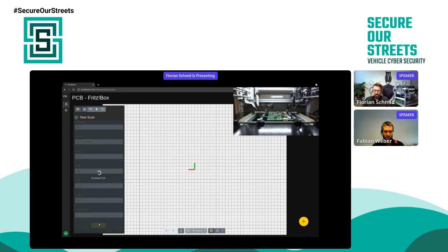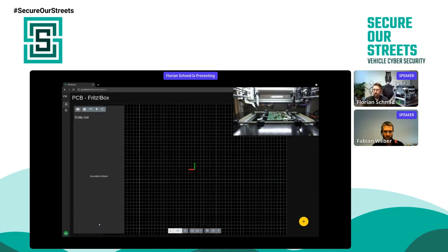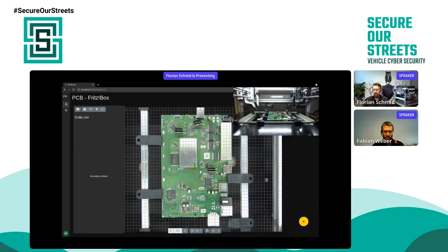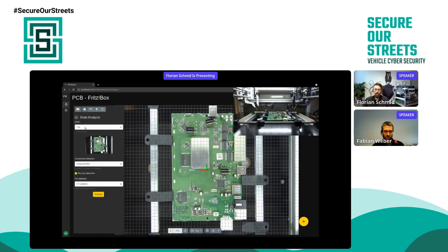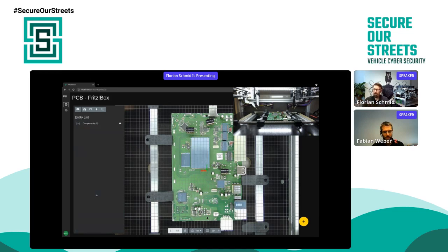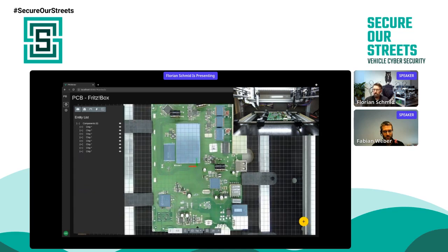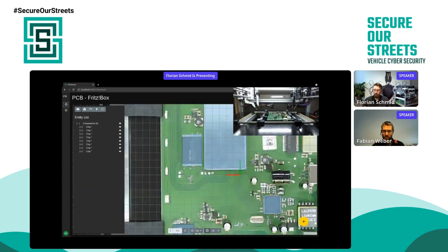So the first thing it does is that it scans this PCB. It makes a photograph of it, and then we can request the PROBoter to run this neural network identification, which I mentioned before, for which you can see here that the PROBoter runs this identification and is able to identify all those 8 components.